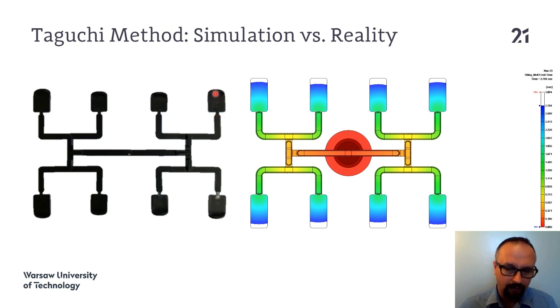It was something about 80% of the whole molding, and here it was something about 90%. It was just calibrated like that because the imbalance is better seen at this stage in the simulation than on that one, probably because of the different volumes we have in reality and in the simulation. Still not everything is considered in our model for injection molding simulation.